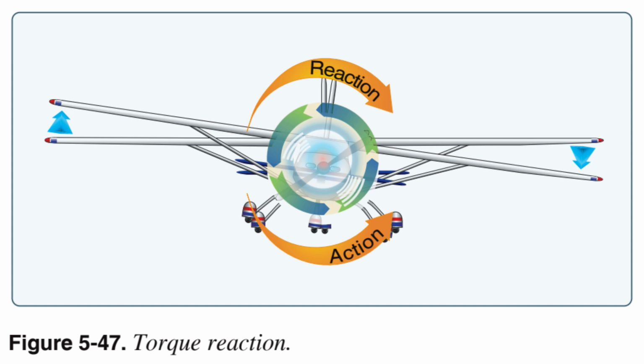Torque reaction. Torque reaction involves Newton's third law of physics: for every action, there is an equal and opposite reaction. As applied to the aircraft, this means that as the internal engine parts and propeller are revolving in one direction, an equal force is trying to rotate the aircraft in the opposite direction. Figure 5.47.